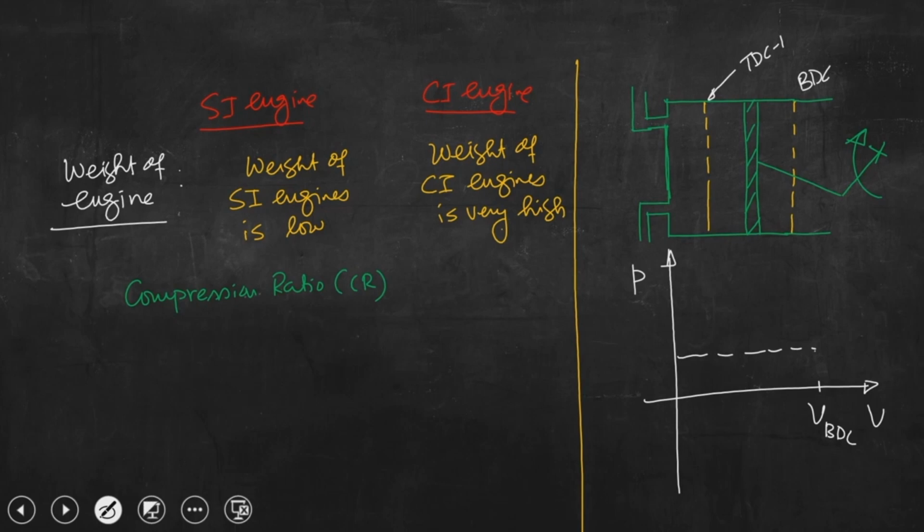So, when piston is coming from BDC to TDC, both valves are closed in the compression stroke, volume will reduce. When piston is at BDC, that is in the beginning of compression stroke, the entire cylinder space is filled with fresh charge, both valves are closed, piston is travelling back from BDC to TDC, volume will reduce, pressure will increase.